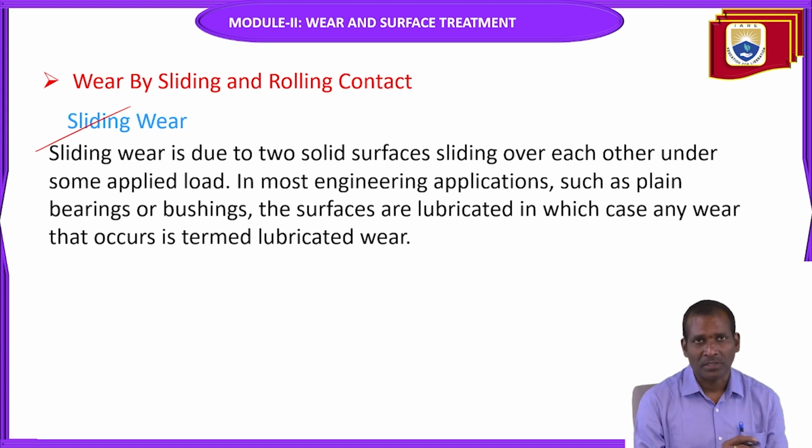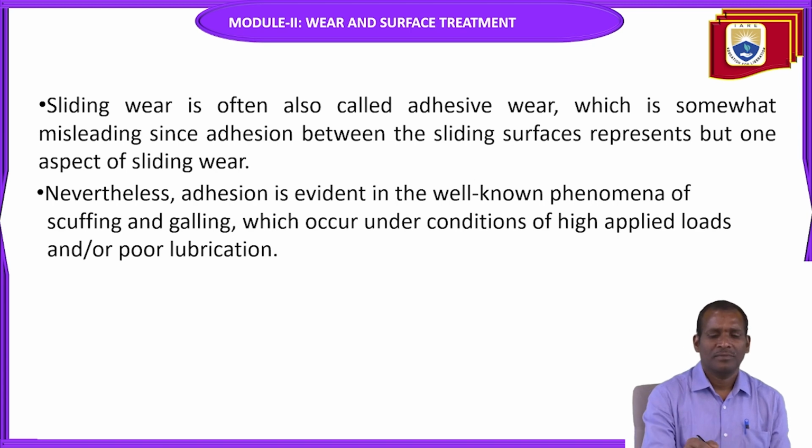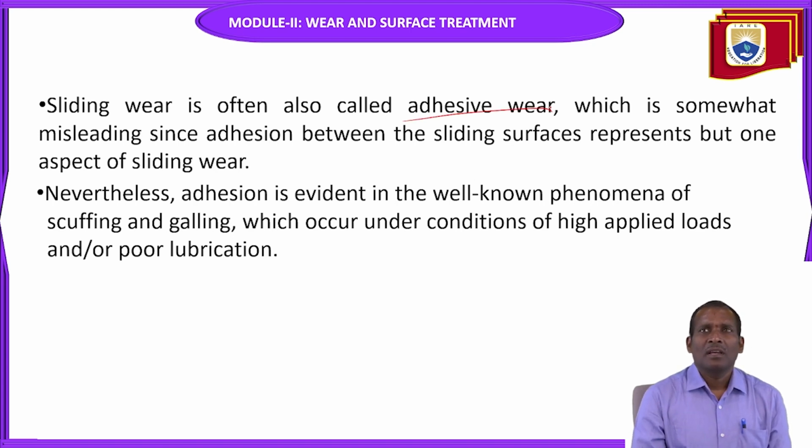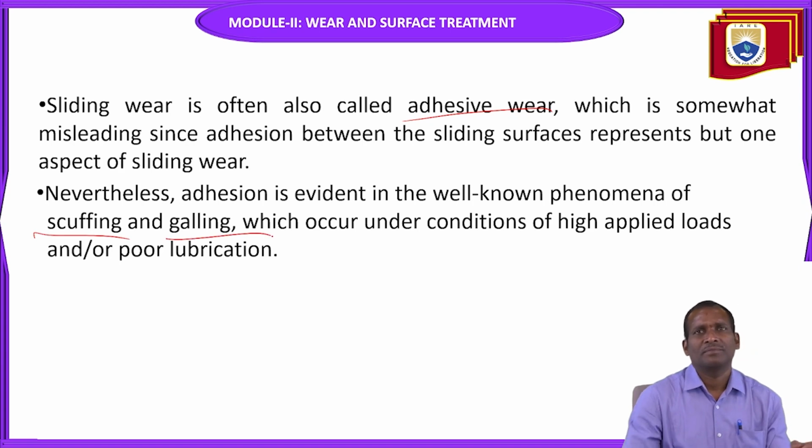Examples we have already seen in earlier sessions. Sliding wear is often also called adhesive wear, which is somewhat misleading since adhesion between the sliding surfaces represents but one aspect of sliding wear. Next, adhesion is that well-known phenomenon of scuffing and galling.